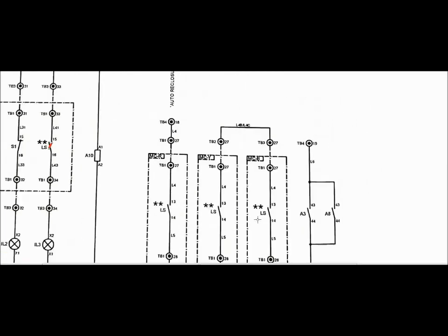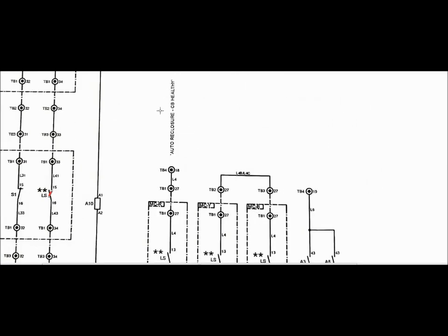Now a CB healthy status is given to the 21 relay for auto reclose purpose, that is, this status should continuously go to the 21 relay as a binary status. If this binary is not high, then auto reclose lockout will go to the circuit breaker, and 3-phase tripping will be done from the distance relay.